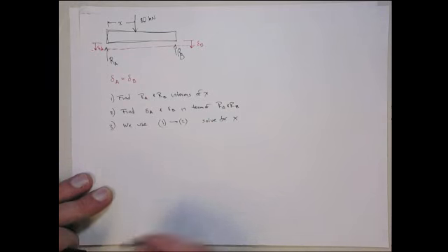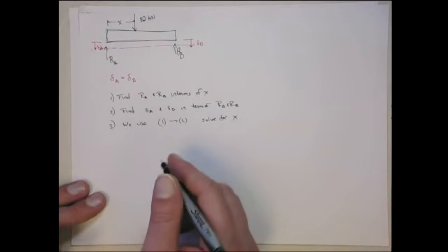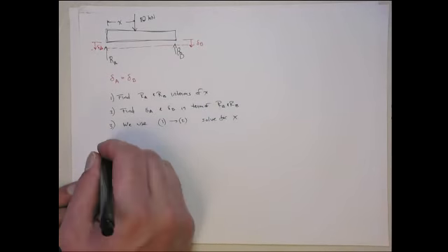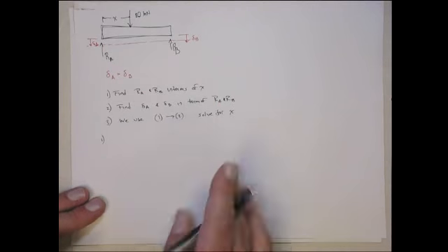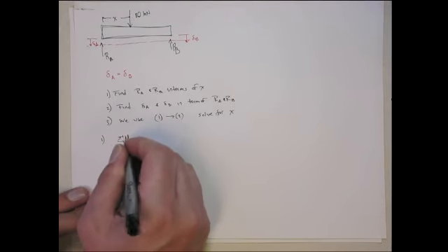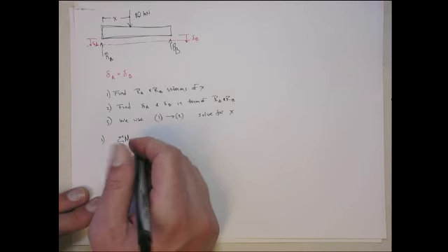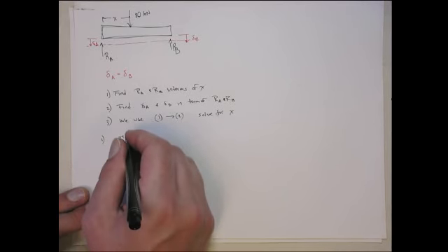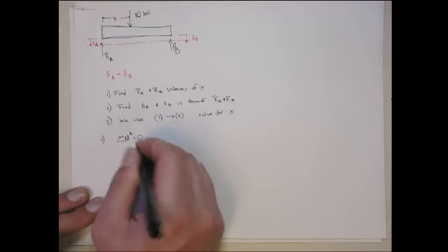All right, so let's do the first part. Let's find the reaction forces in terms of X. So let's do a sum of moments around point A equals 0.